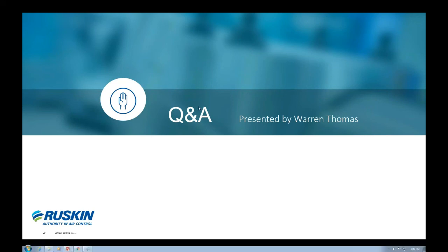There's a question here asking, how often are steel sunshades used? I will see requirements for steel sunshades, but usually the desired shapes are not as prevalent with the steel, and so they end up becoming very basic and being very limited in your exposure. So the most prevalent is going to be an airfoil aluminum sunshade. It looks like we don't have any more questions.